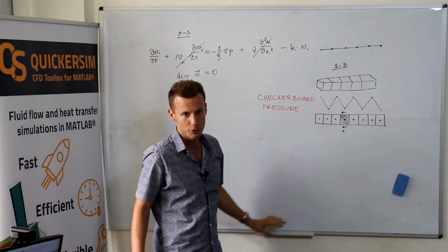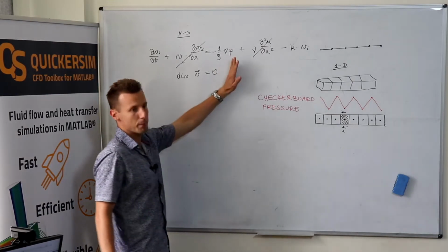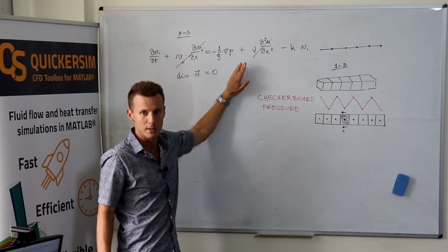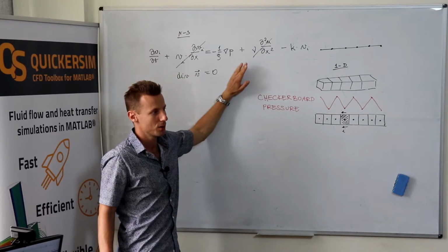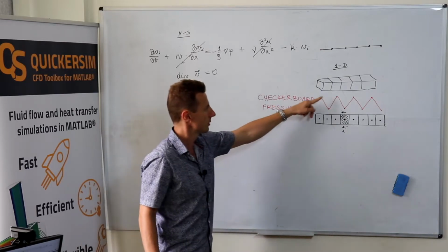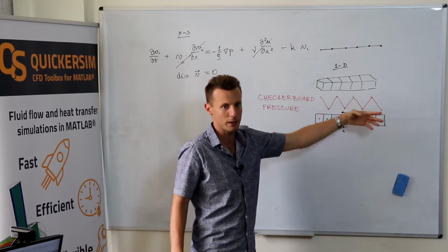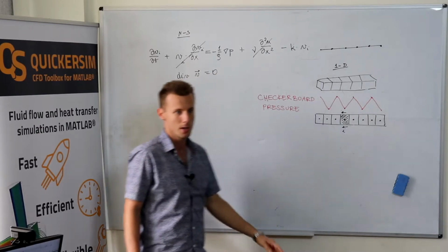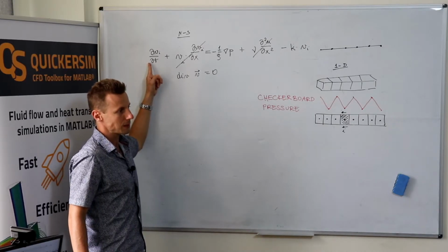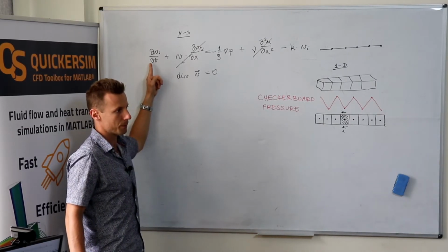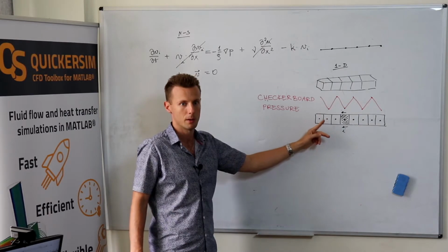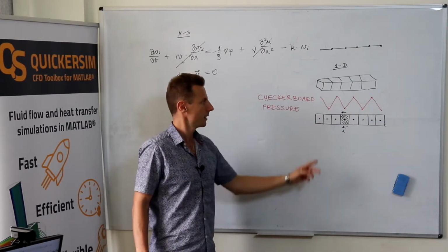So this means that generally your discretization, the matrix that would come out from such a discretization, is a singular matrix. You've got infinitely many correct solutions to the problem. Whatever similar pressure pattern you generate, this will satisfy your equations, and it will induce no flow whatsoever. So you've got singularity in your problem. The problem is not well defined, which means that the algorithm is not okay.